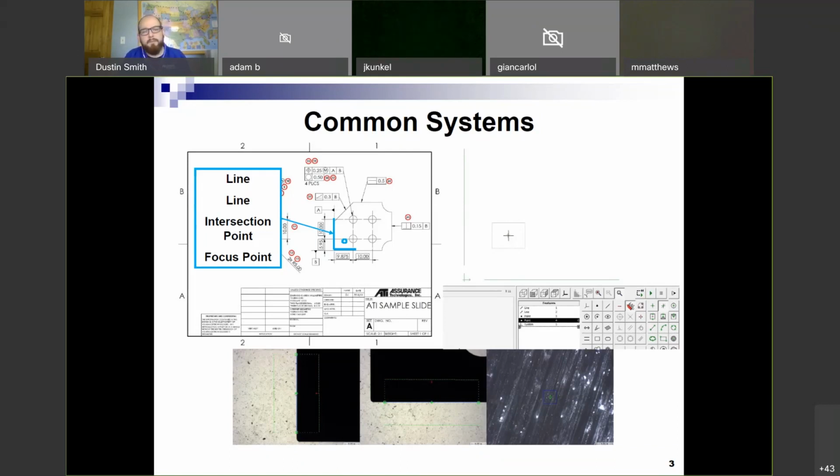It's very important to hit that focus point on top of the part, because if you write a program on just your glass stage, and then you end up getting fixturing for it, putting that focus point and origin of Z on that part will allow you to move that part to different Z heights on your fixture, and the program will repeat and run, with a little adjustment the first time you run it, but it helps make that program solid.